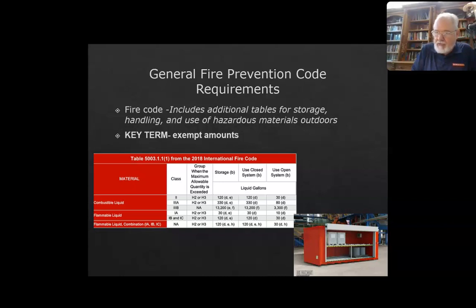Is the indoor area protected by an automatic sprinkler system? 4. On what floor is the control area located within the building? 5. Are the hazardous materials kept in code-compliant storage cabinets? 6. Does the area have proper ventilation and safeguards for spill control and spill containment?